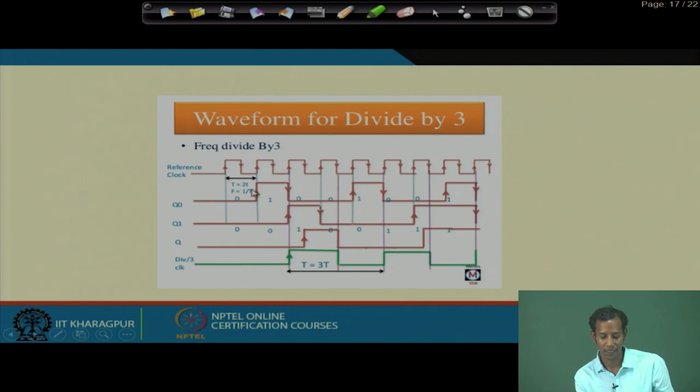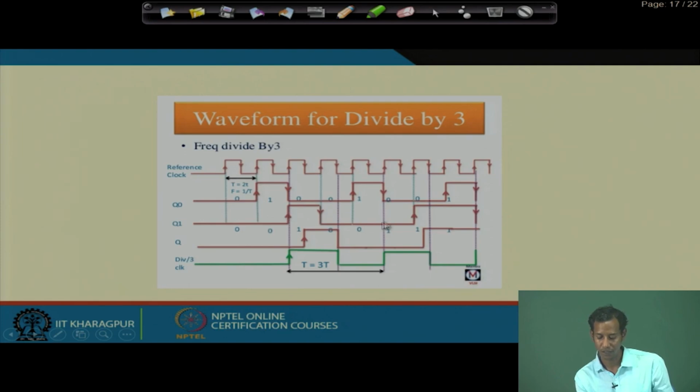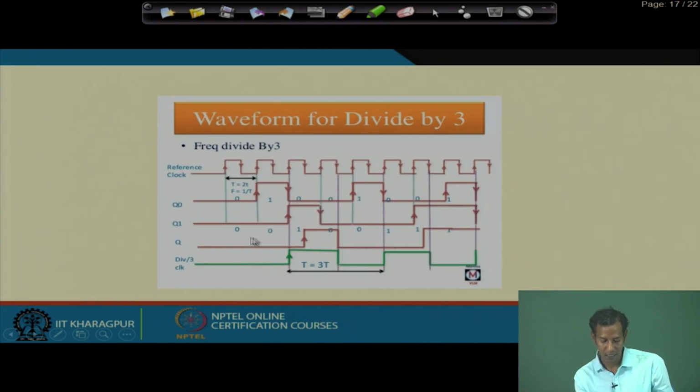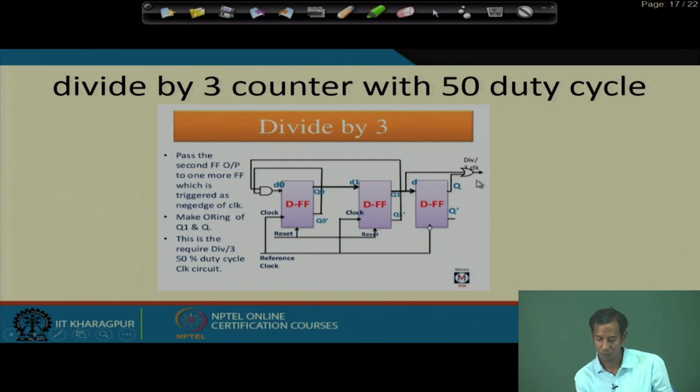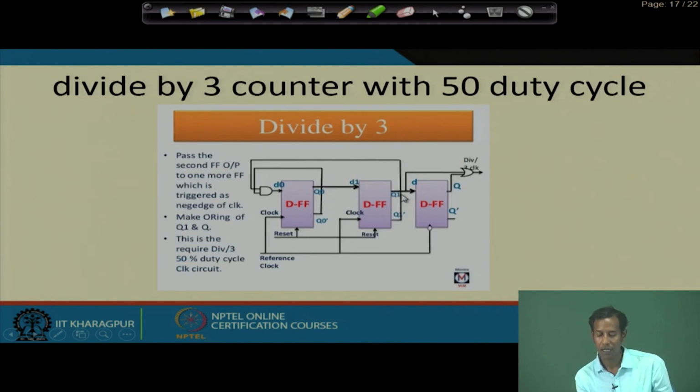So, depending on that, the Q0 value will be something like this. And what is the Q1? Q1 is nothing but the Q0, which is 1 bit, 1 clock cycle shifted. So, this is nothing but this, okay. And then you will be getting the corresponding Q. Okay. So, what is this Q? Q is the output from the third one. So, Q is dependent on the Q1.